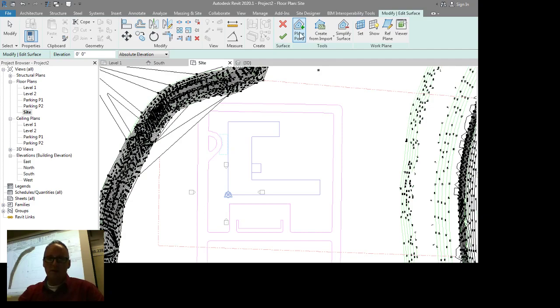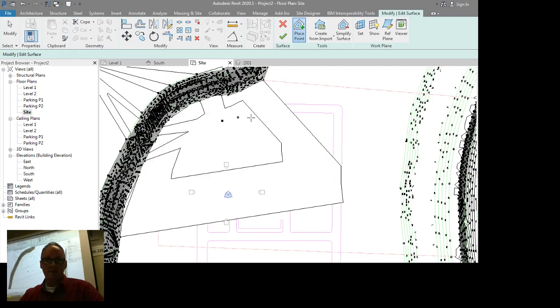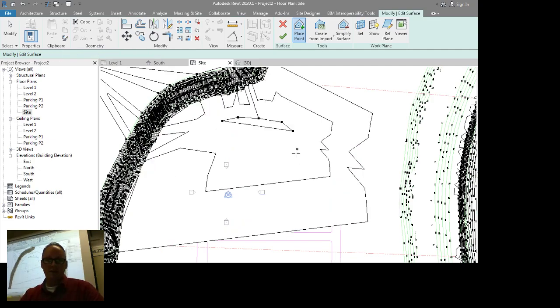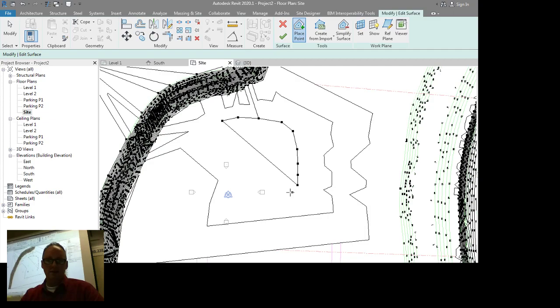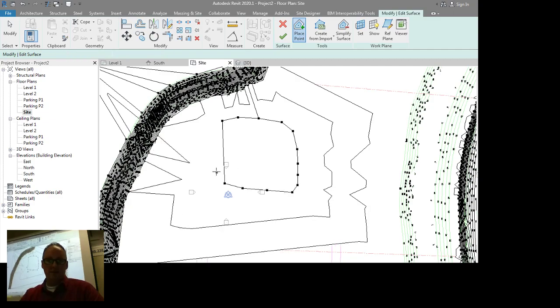So with the place point tool, you folks can specify the height of the point that you're adding to the topographic model. And Henry will probably have shown some of you in the intro course how to add some additional points around that initial model that you made in the intro course. And so here we're kind of going through that same process, placing points, giving them an elevation of 2 feet, and placing a few of them around the outside of the building. And you can see that it's regrading the model. We're adding some height there.